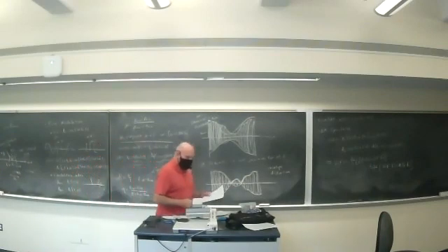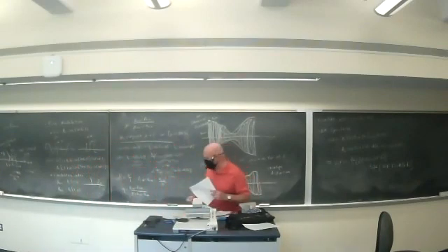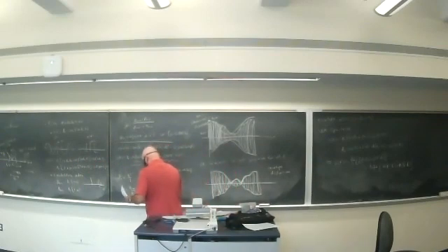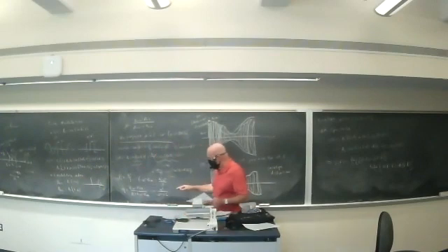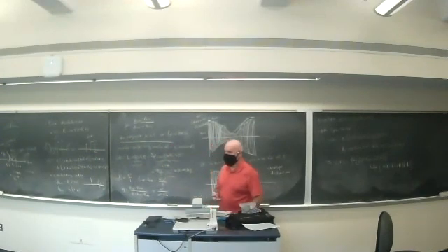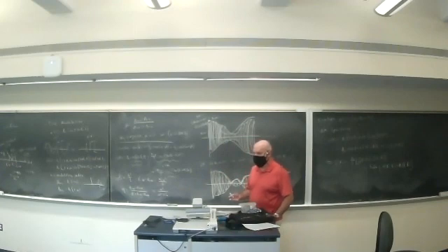If you plug in terms of mu, all the ACs cancel, you get mu squared over mu squared plus 2. If you take the limit where mu is at its largest value, this becomes 1/3. So the maximum efficiency of AM radio is 1/3.